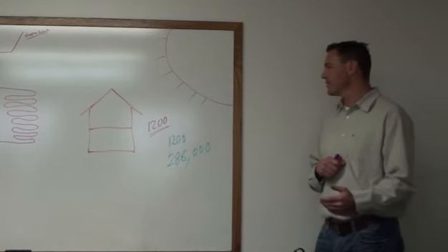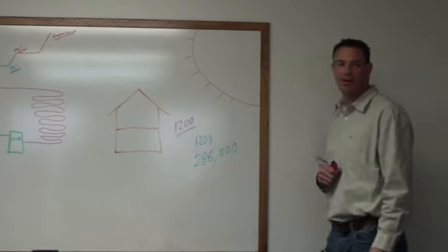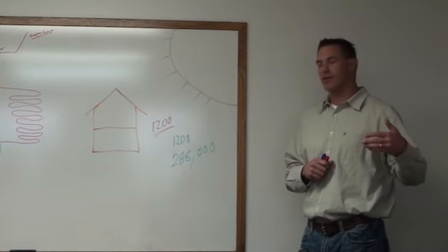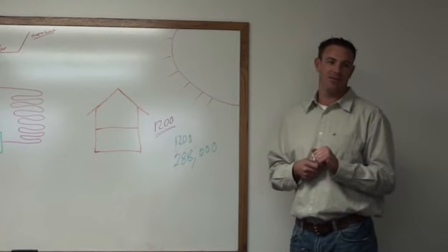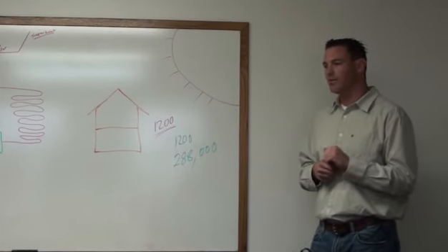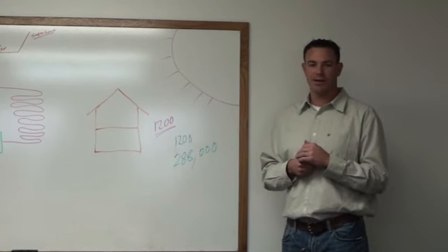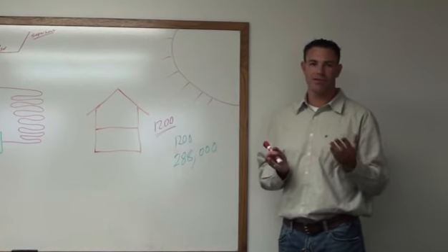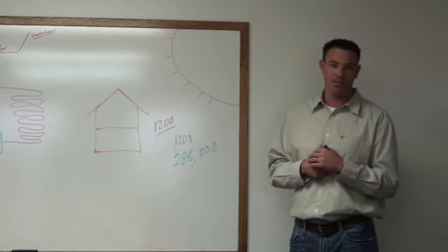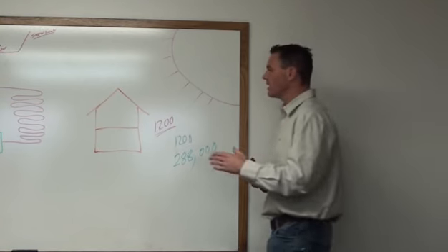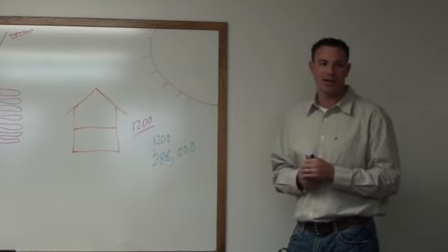So for us to displace the heat that this house is absorbing from the sun, we have to have the ability to remove 36,000 BTUs of heat per hour. Okay, so if you guys take our initial model that we're going to probably hit the streets with, it's 12,000 BTUs, which is roughly a ton of cooling. So if you take and put a unit in a 1,200 square foot home and expect it to take